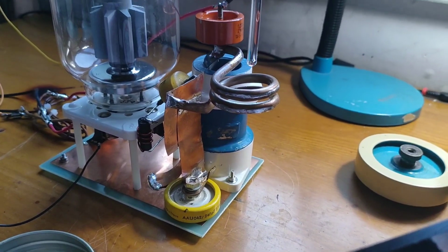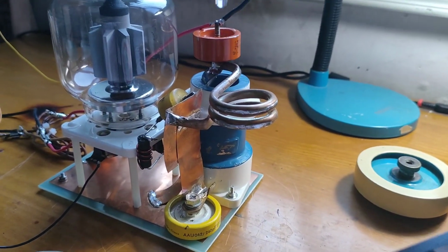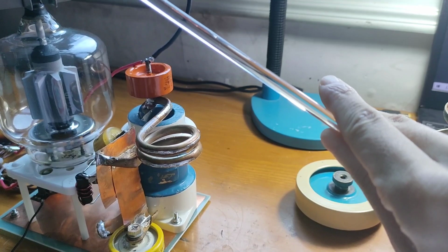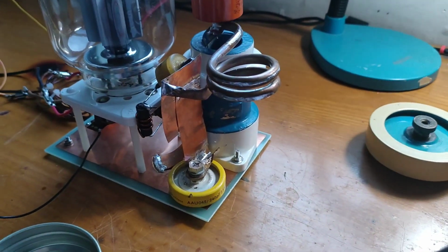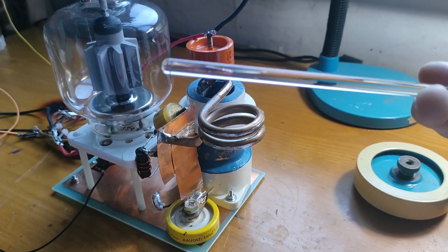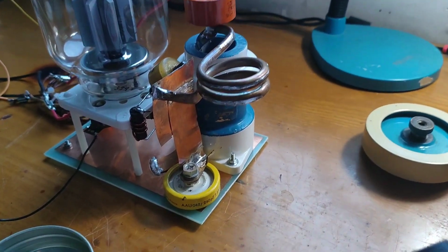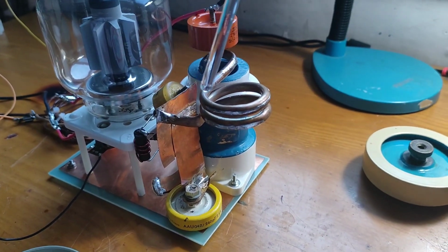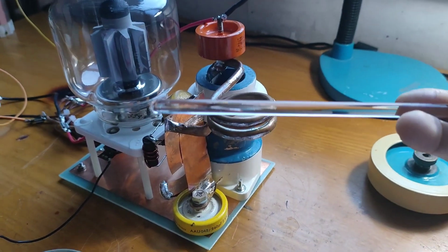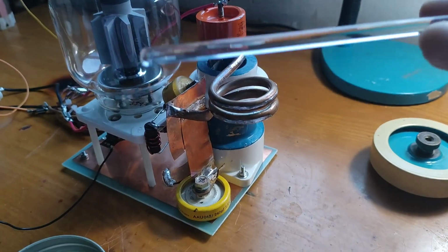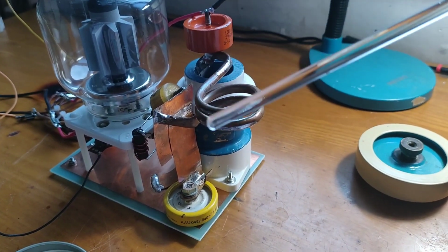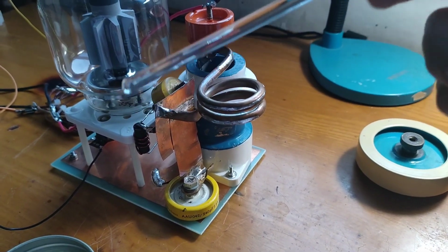You will see the cathode current normally goes up, but in some situations the current will go up and then suddenly go down. That means the feedback is not enough and the oscillation actually stops, or it just stays on some parasitic oscillation frequency. In that situation, you need to increase the feedback. But if you are doing that at a fairly low voltage than designed, the cause might be the same reason, not enough feedback, but the reason might be just that the voltage across the tank is not enough to sustain the oscillation.